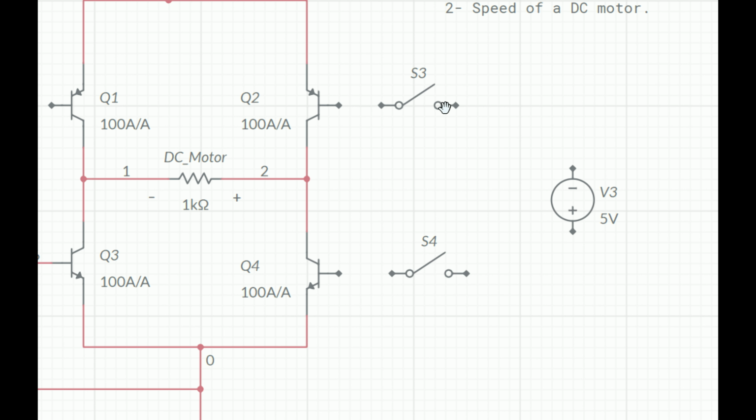Now take a look here. No transistor is triggering right now, no base is connected. It is open, all the switches are open, as we have not sent any value from the microcontroller. A PNP transistor only triggers when we get either a 0 from the microcontroller, or the gate or base pin is connected to the ground. In case of a MOSFET, it will be the gate, and in case of a BJT, it will be the base pin.